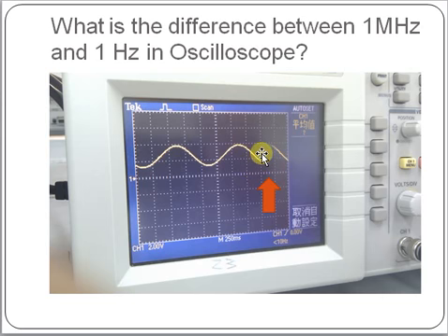The oscilloscope drawing speed is related to the frequency of the input signal. When observing the 1 Hz signal, because it is a low frequency signal, you may see the oscilloscope draw the signal from left to right. On the other hand, when you are observing the 1 MHz signal, you may see the signal shifting left and right very fast. This is because the drawing of the oscilloscope is very fast at high frequencies. Therefore, we have to use the concept of trigger to make the signal still.